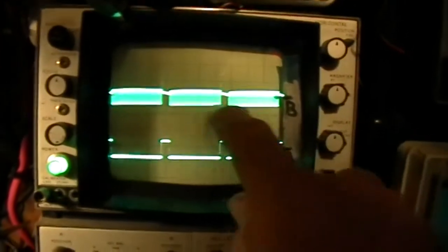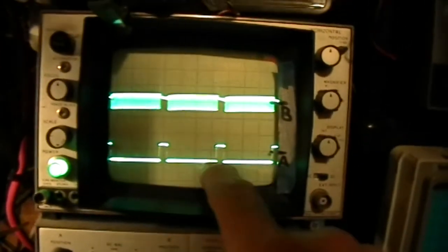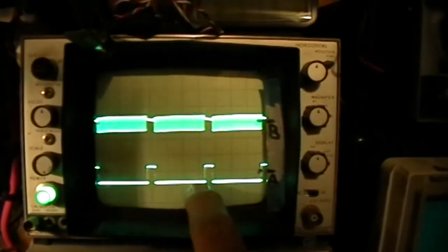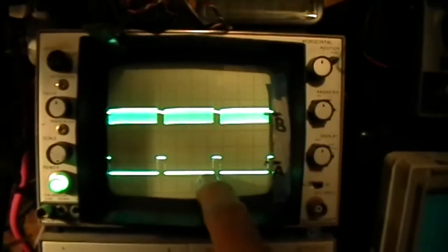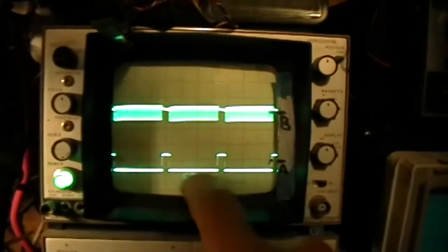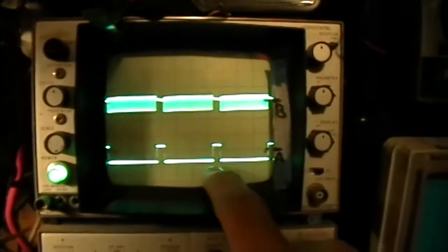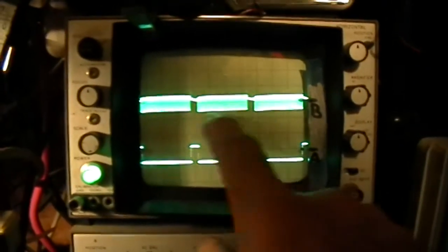But the more negative offset I apply, the more current we're actually putting into that clipping, and that's what causes the oscillations. Whatever part of the circuit is causing the negative voltage supply from the function generator not to go below 4 volts negative, that's injecting current into the system, negative bias current, and that's what's causing the oscillations in the Q2s.